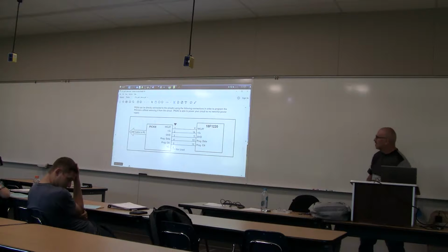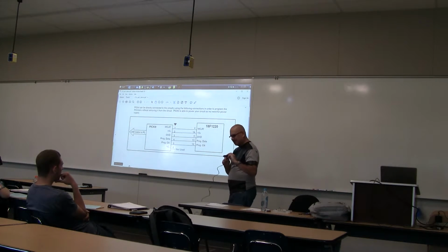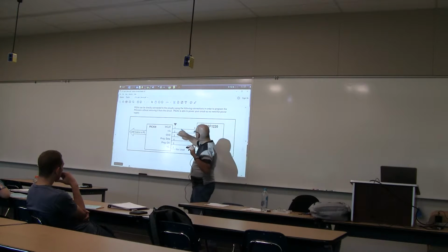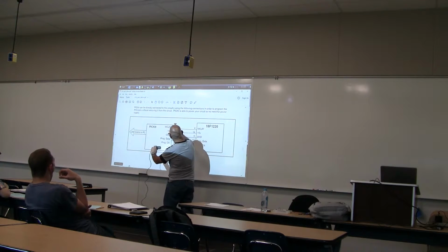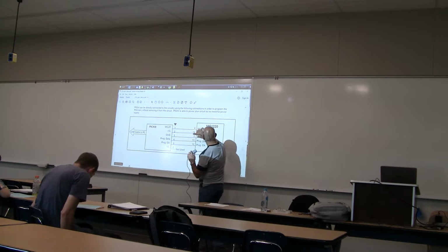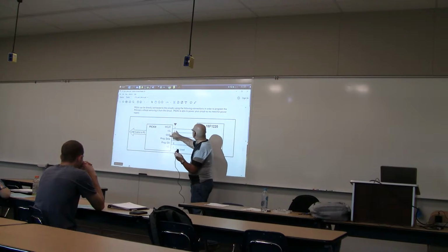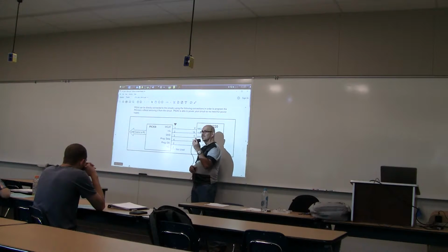All right, so to hook this up, you need to run some wires. So if you look at the front of this, there's a little port with 6 holes in it, and there's a triangle sitting on top of one of these holes. That's this triangle here. So this is the PicKit programmer, and this line up here goes into this top hole next to the white triangle. And it connects to pin 4 on the PIC chip. Okay? The second hole, pin 2, goes to pin 14 on the PIC chip, 3 goes to 5, 4 to 13, 5 to 12, and the bottom hole is not used.